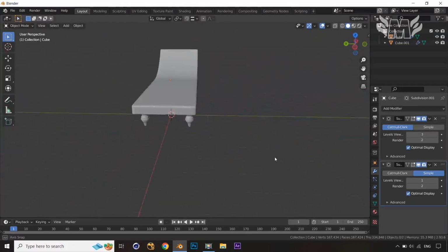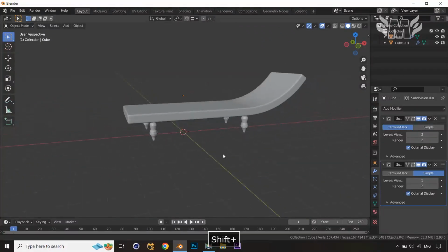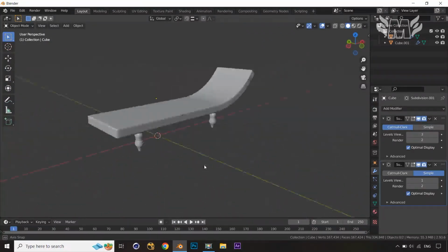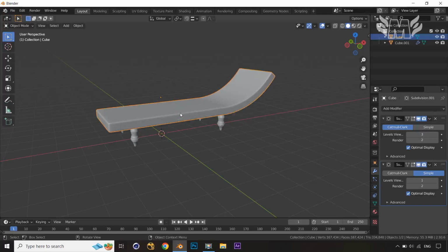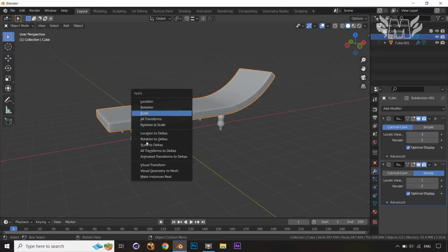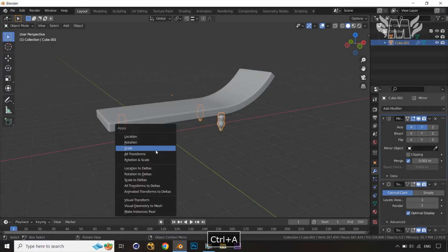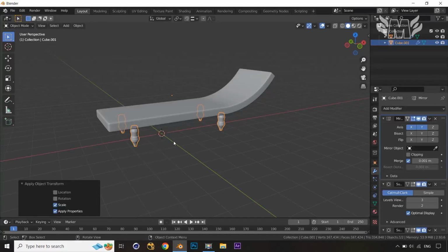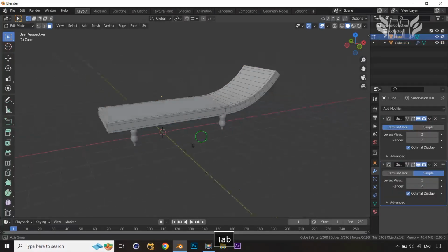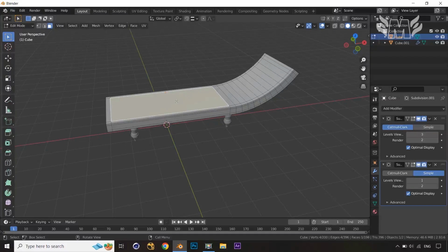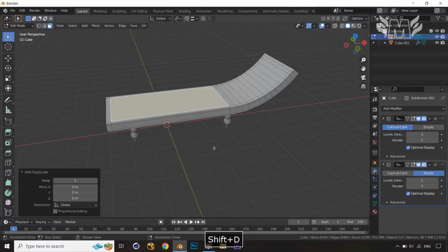Now we are just going to apply some simple texture on this one. That is a really simple and better way. First of all select this, Control A and apply scale, then select this, Control A and apply scale on this one. Okay, now you can create one pillow also. So apply the 3, then press Shift and D, separate it with P and separate selection.